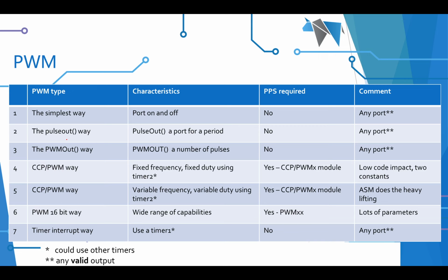So you can just set the frequency, set the duty cycle, use this timer 2, and literally you set the PPS, job done, works. And you can play with that. It's a great tool to play with in terms of fixed frequencies. And if you're smart enough, you can actually change the frequency as well. It's extremely simple to use, and I'll show you a program that helps you.